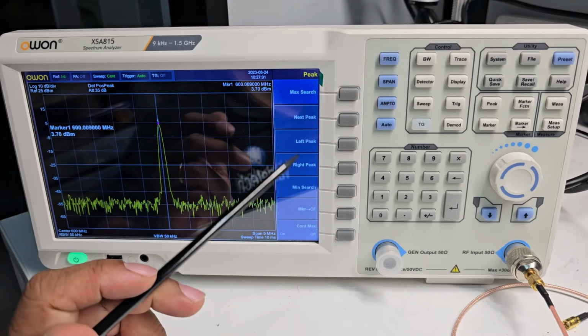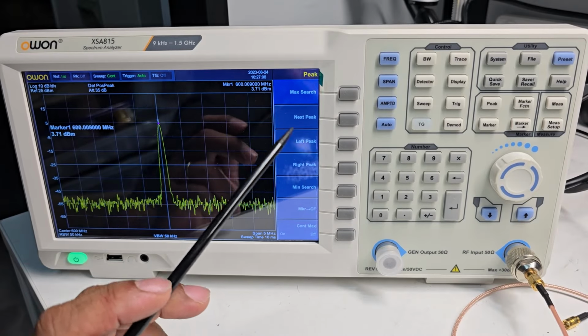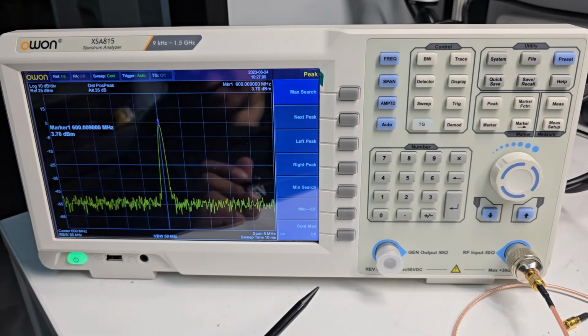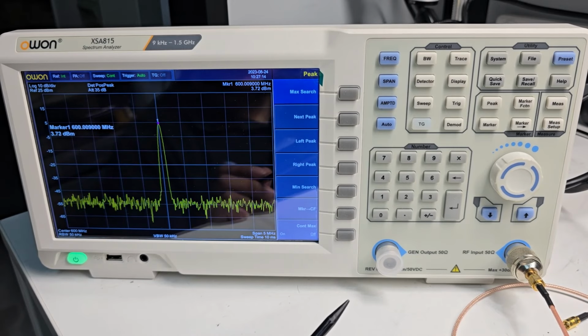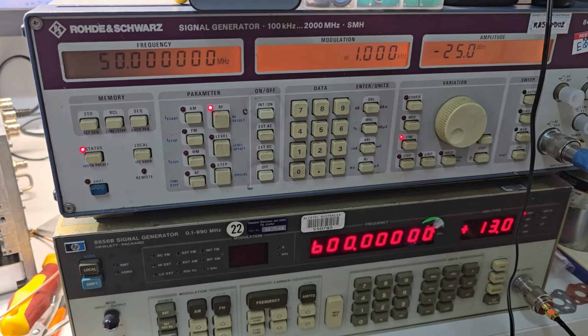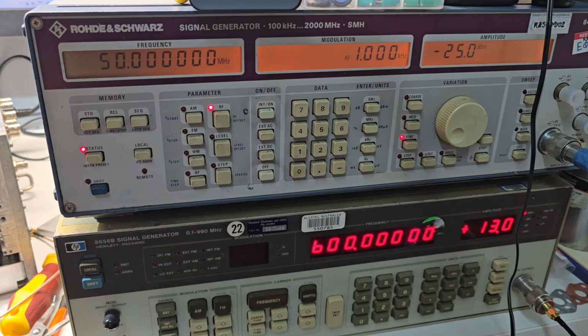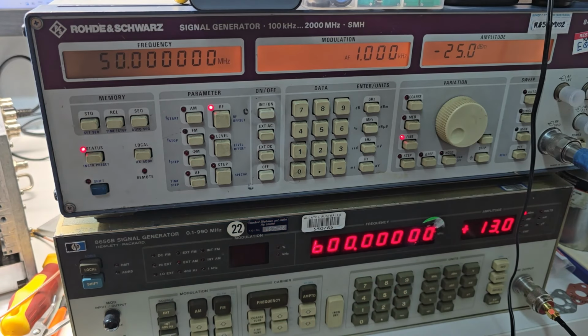So we definitely have a problem with the amplifier on the A11 reference board. The required level is 13 dBm plus or minus 3 dB, so we are really out of that signal. So what I'm going to do is inject 600 megahertz frequency at 13 dBm into the A11 600 meg coming out, and into the A9 second local oscillator board.